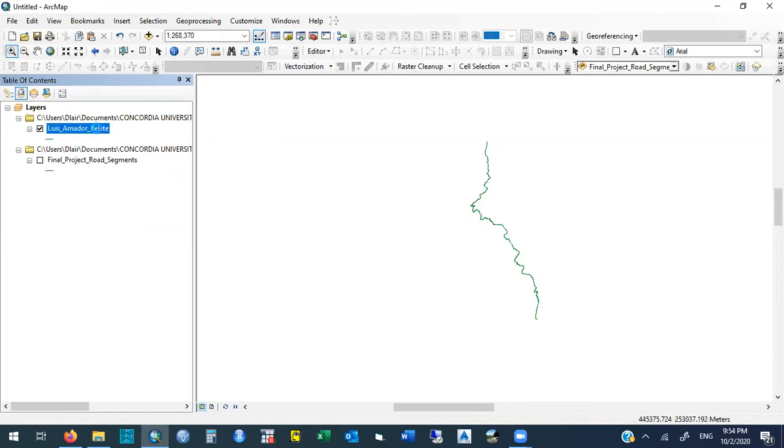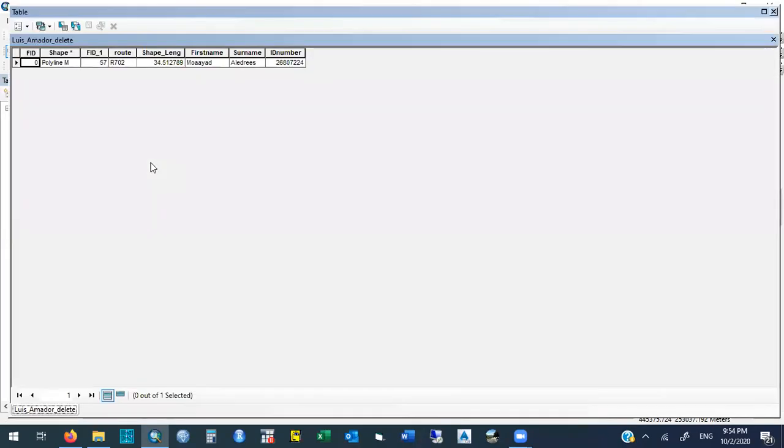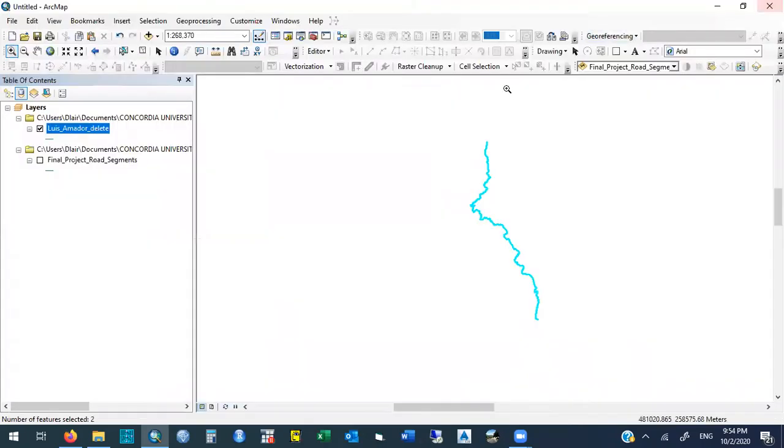Now, this segment right now is only one whole segment. This one is 34 kilometers, actually, it's a bit long, okay? So we're gonna break this in maybe, what can we say? Maybe 500 meter, maybe 200 meter segments. And then we're gonna create midpoints for each segment, and those midpoints we're gonna import in Civil 3D. How do we do that? So first we need to split this.